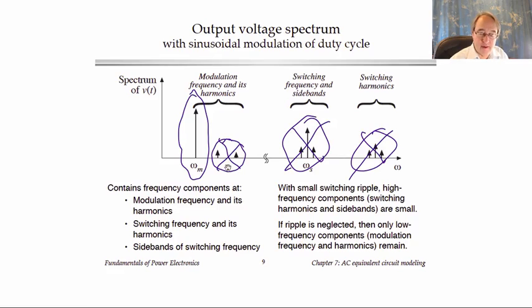The reason for that is that otherwise our differential equations for the converter dynamics are nonlinear, and we can't simply take the Laplace transform and find transfer functions. So what we're going to do is similar to what is done in an electronics class in modeling other nonlinear elements such as transistors and diodes: we construct a small signal model in which we ignore these low order harmonics and linearize the circuit. So then this is in the end the only thing that we want to model.